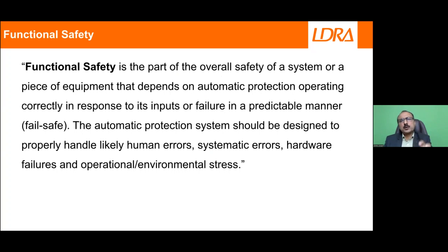But I spoke about the impact of failures at the component level, right? Each subsystem when it fails. So if I break it down to each subsystem, and based on the impact of those failures, what level of severity those failures have at the subsystem level, if I am able to make an assessment for a safety parameter, that's where the definition of functional safety comes in. So at the ABS, at the traction control, whatever you are doing, even a tire pressure monitoring system, at every subsystem level, if I go deeper into that, I first do an assessment of what is the impact if this fails, right? So that decides my safety integrity level, which level I need to put it.